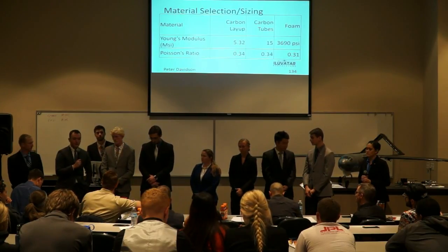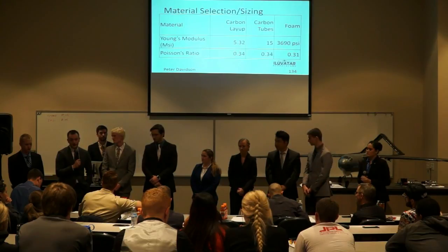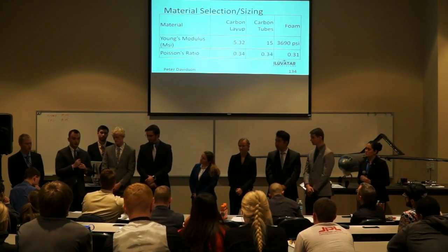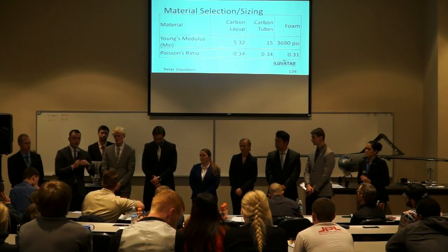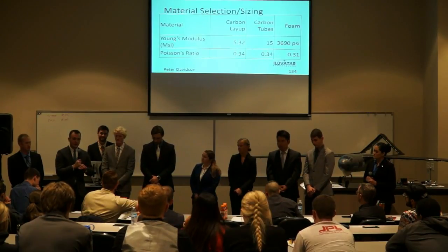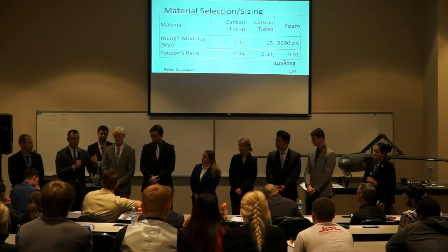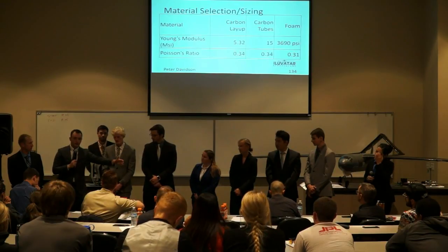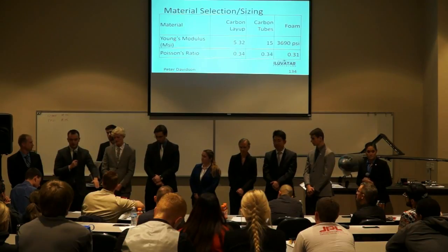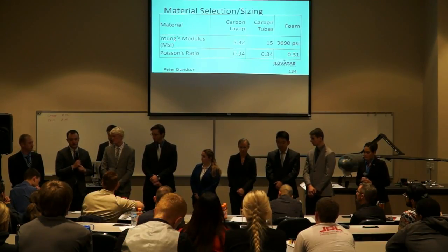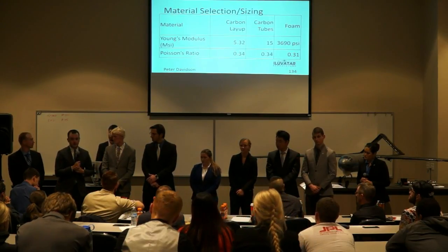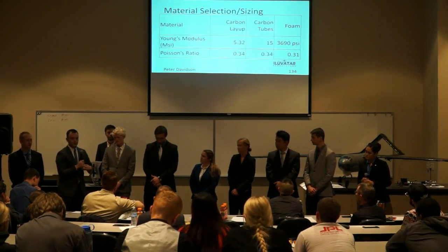And we believe that to be due to the ferrule not being sized large enough, and in addition, that there is some play in the tubes. They're not tolerance tight enough, or they're not epoxied in the right way. That little half a degree of play, over the 7 foot per wingspan, is multiplied into a very large deflection, and that was not accounted for at all in the ANSYS model. So that's another reason the wing deflects so much in the actual structural test.